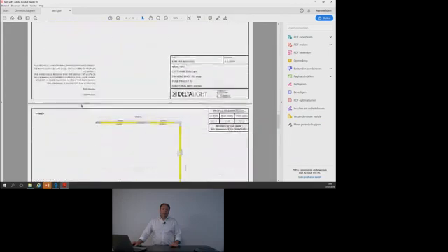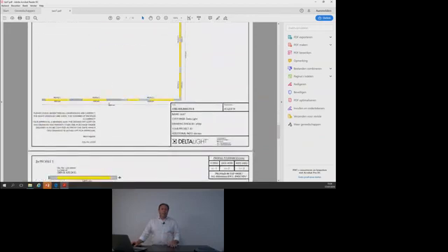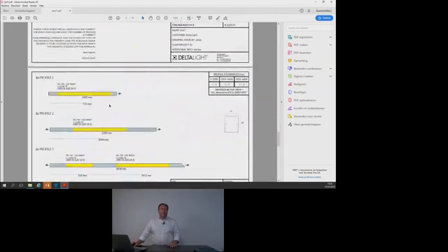And if I go further, then I have the same construction again, but this time it shows you the uplight. So this is the uplight. How the uplight is divided is calculated by the profile builder based on the lengths, based on some restrictions when you are using cable suspensions, etc. So when there is a cable suspension, there cannot be an uplight, and this is all calculated within the profile builder. And then I have again the same individual parts.